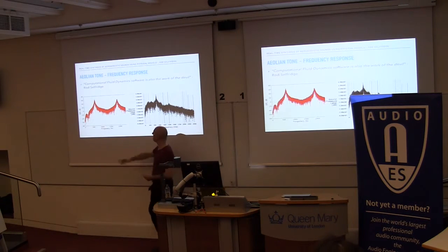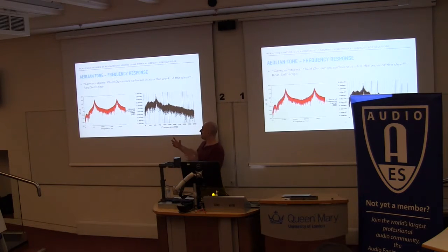So we can see a problem here in my model. I have seen plots that are very similar and do have these harmonics far more visible on this one, and the reason I believe mine is probably inaccurate is because the Reynolds number is so high that the harmonics' gain value comes right down. I couldn't see the exact Reynolds number in the Harden paper when he states these, but I believe it's far lower than what the Reynolds number is in this particular physical case. The Reynolds number is about 33,000.